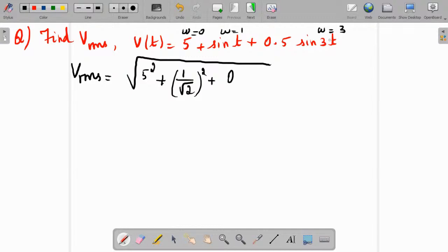Okay, similarly here let us finish this question. So here, what is V average? There is no DC component here, so V average is equal to 0. Okay, average voltage is 0 in this case. Whereas in this one, only a single signal is given. Here it is a combination of signals: 10 plus sin t plus sin 3t, and here it is 9 sin t plus 4 sin 3t. Okay, you have a set of sequence of signals, but here you have a single sinusoidal signal.